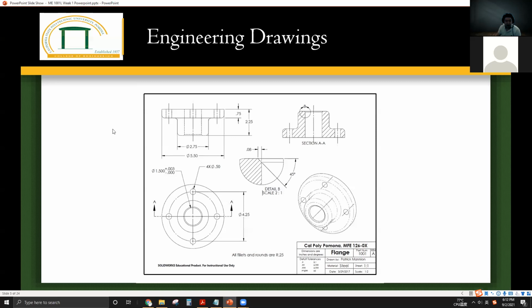So let's look at this, the 1.5 diameter. The reason we want it to have its own tolerance is because we want this surface to be well controlled. So you can see the total tolerance on this dimension is only 3 thou. That's very small, so it must be very precise. But for the thickness, since we don't really care about thickness, or we don't care that much, we give a 30 thou tolerance, that's okay, acceptable. So it's also cheaper to make the part.